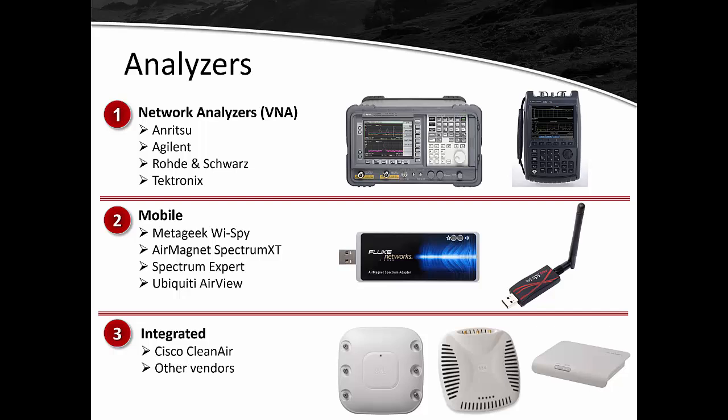Now the good news is you might think, well, wait a minute, do I need to get a new spectrum analyzer every time there's a new version of 802.11? That is to say, do I need a new spectrum analyzer every time we go from 11n to 11ac to 11ax and so forth? Well, the answer to that is no. You do not need to get new spectrum analyzers every time, and the reason is because we're looking at the RF energy. We're not looking at frames.